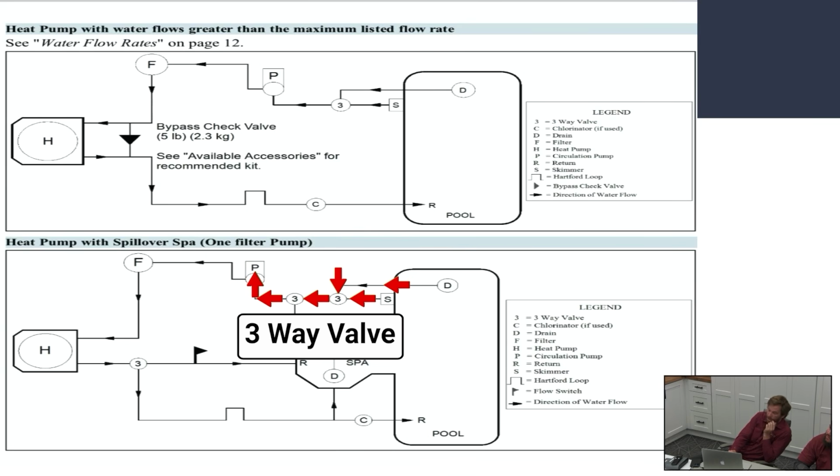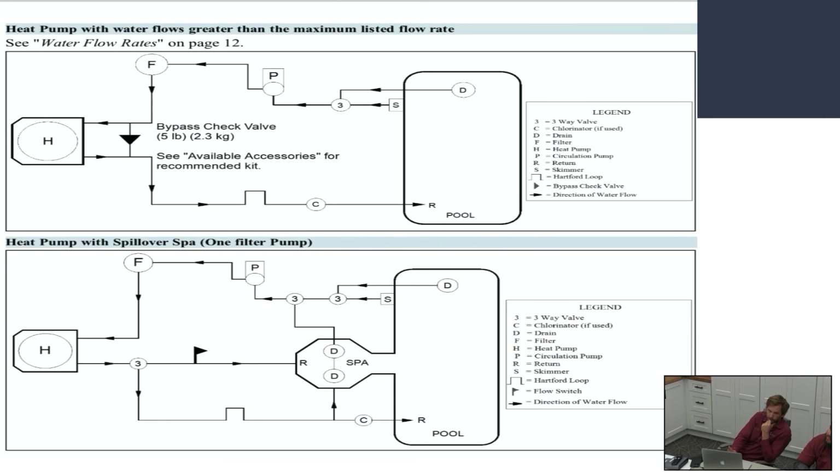So you'll have a set of valves. And often a pool will have two drains, so there'll be two Ds and one S, coming into a set of valves right before the pump. And that valve there is where you could turn it off to one of those pipes coming in. It would turn it off to that skimmer, right?